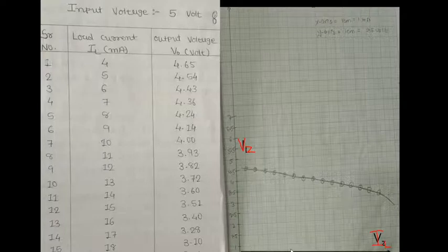this range of load current is the very stable range of your voltage. That means within this range of current, our present Zener diode can work as a voltage regulator. That means it can regulate the voltage. The voltage will remain constant. So this is how you have to learn it exactly.